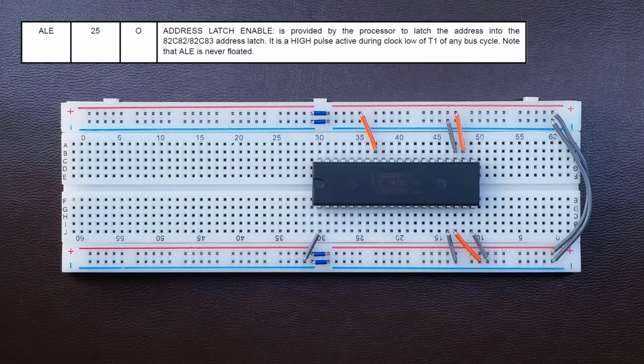Pin 25, ALE, stands for address latch enable. It is an output, active high, a very important signal which allows us to latch, or remember, the memory address asserted by the CPU before the same lines are used for transferring data in the next clock tick. You may remember what we said a few minutes ago, that the x86 shares the same pins between the address and data bits.